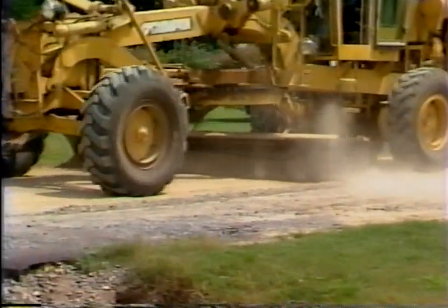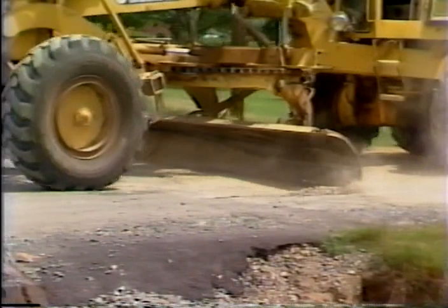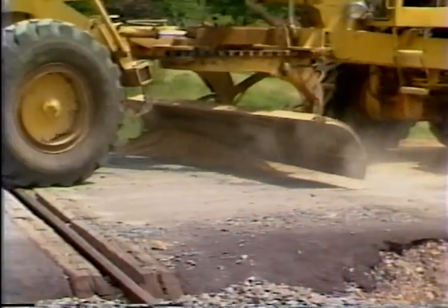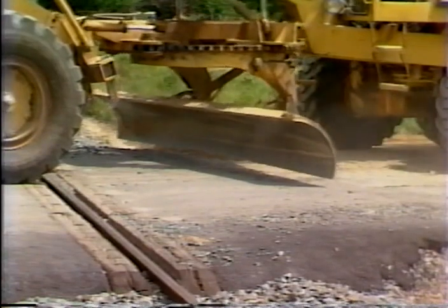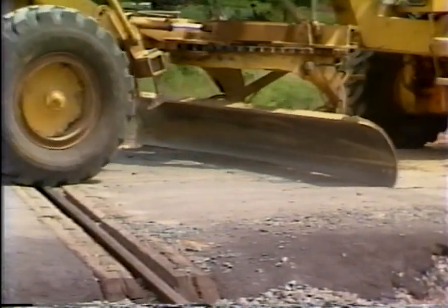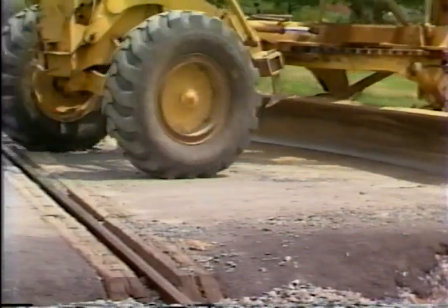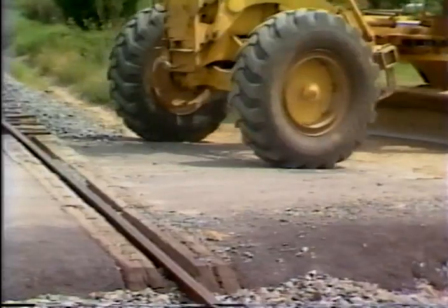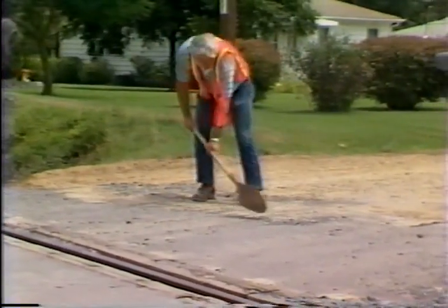The material may need to be backbladed to smooth the crossing area. Push material up to the edge of the crossing area, then lift the blade over the material and place it down in front of it. Backblade the material in the reverse direction, smoothing the material out from the railroad crossing. If necessary, use a shovel to remove loose material from the tracks.